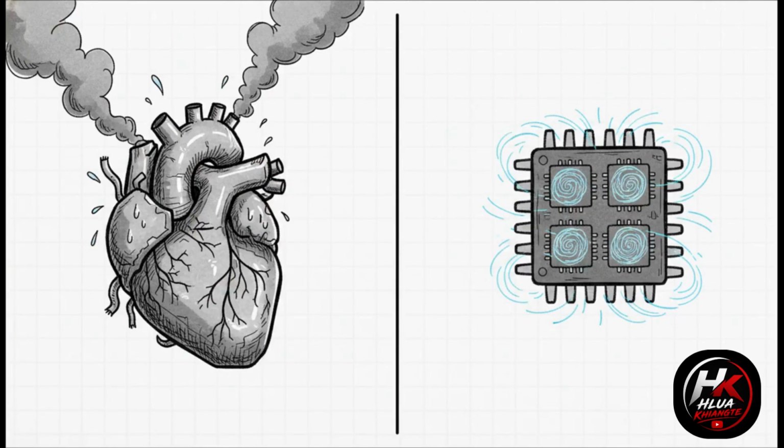So how did the industry bypass this thermal nightmare? Well, they pivoted entirely to multi-core designs. Instead of trying to build one scorching hot, super fast core, they placed multiple, slightly simpler cores onto the exact same chip. These cores can run instructions in parallel, and because they operate at a lower frequency and voltage, they dodge that destructive power wall entirely, resulting in vastly better performance per watt. It's exactly like replacing one exhausted, overworked draft horse with a team of 4 well-rested horses all pulling together.